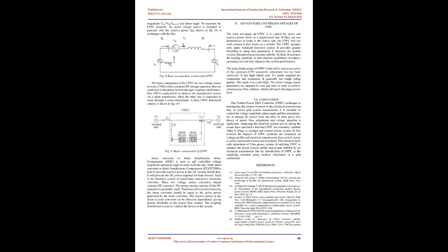Real and reactive power flow control using UPFC. A simple two-machine system with sending end voltage Vs, receiving end voltage Vr and line impedance X is shown in the system voltage in the form of a phasor diagram with transmission angles. The system of Fig 7a is used as a building block to explain the capability of the UPFC to control the real power P and reactive power Qs and Qr at the sending end and the receiving end of the line respectively, included with UPFC. The UPFC is represented by a controllable voltage source in series with the line.